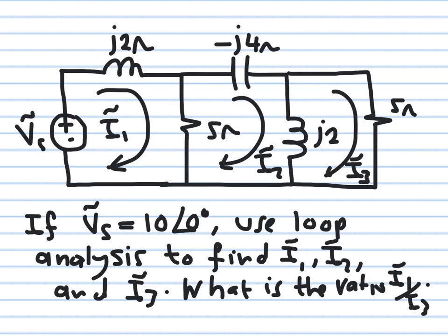But as I said in class, in most of these problems, if you write the system of equations, you'll get pretty much most of the mark, as long as you did everything in a correct way. But of course, sometimes we ask you for other things, like calculating a voltage drop or something, so you're probably getting the currents. You have to know how to do that through either Gauss elimination or using your calculator or using direct substitution, whatever the case is. So we start to write KVL for loop 1, loop 2, and loop 3 to get 3 equations and 3 unknowns.